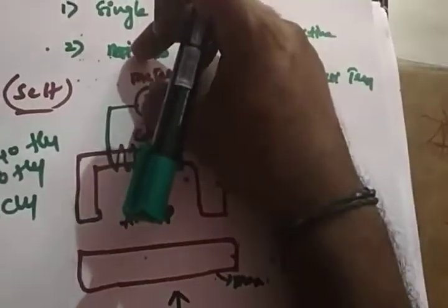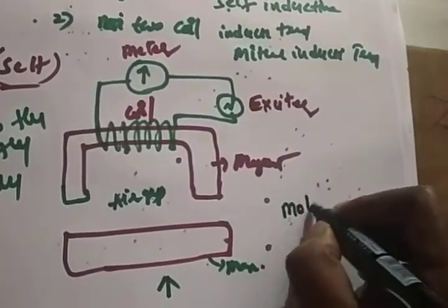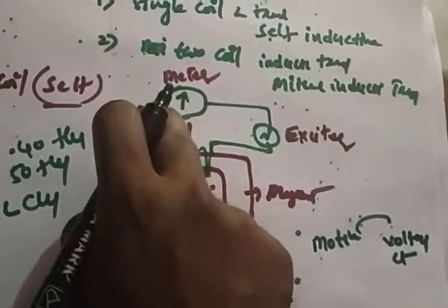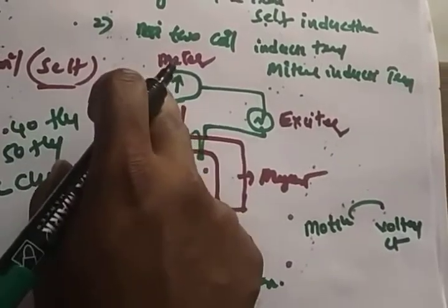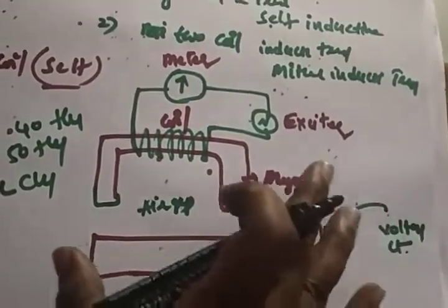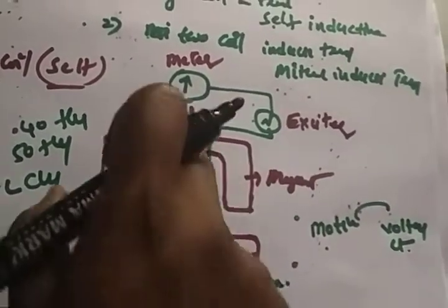So this inductance can be calibrated on the scale over here. Whatever the output of the scale is equal to the motion, that means the motion is converted to voltage or current, whatever the meter is. If you take the voltmeter, it is voltage; if it is an ammeter, it is current, right? The motion, which is a non-electrical quantity, is converted to an electrical quantity. So that's why we can call it an inductive transducer. You are converting the motion into a change in the inductance.